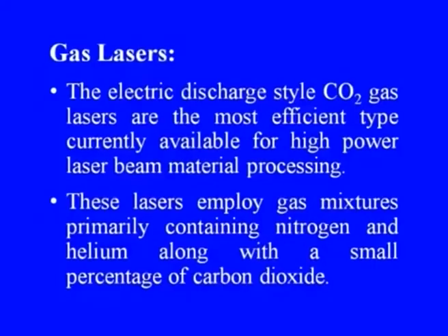Now, let us talk about the gas lasers, which are widely used in laser beam welding. As we have already indicated, carbon dioxide is the most popular gas laser. The electric discharge style of carbon dioxide gas lasers are the most efficient type currently available for high power laser beam material processing. These lasers employ gas mixtures primarily containing nitrogen and helium, along with a small percentage of carbon dioxide.